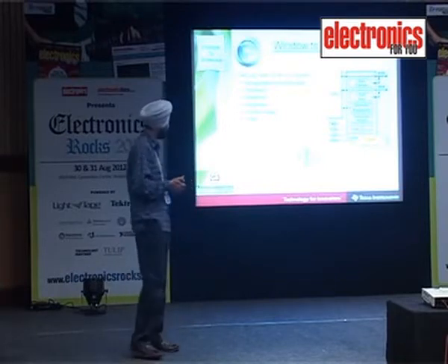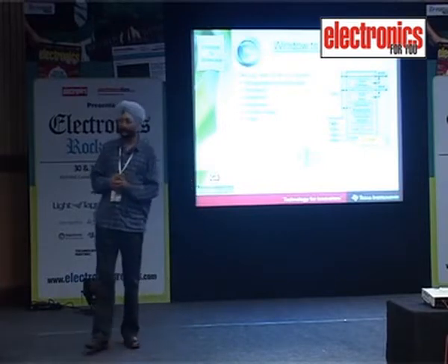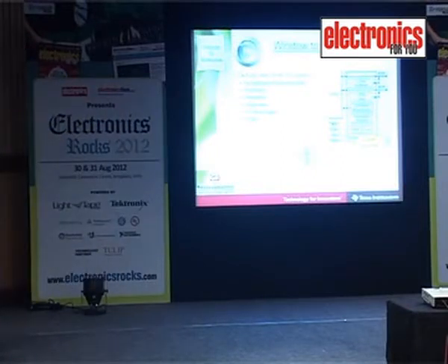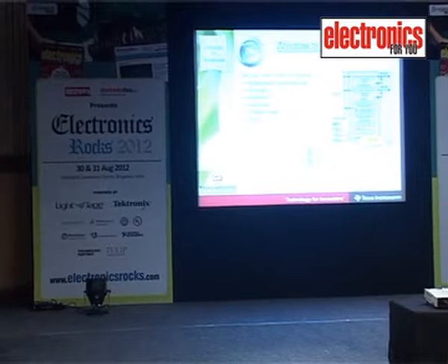So you can put in breakpoints. You will be able to check the memory, RAM, flash. You will be able to make changes. Even, sometimes, let's say some hardware is connected to your chip, and after running the program, if the hardware is not working, you will be able to stop the program. You can just force some values into the ports, and you can see whether the port is really working or not working. So those things are possible because of JTAG.